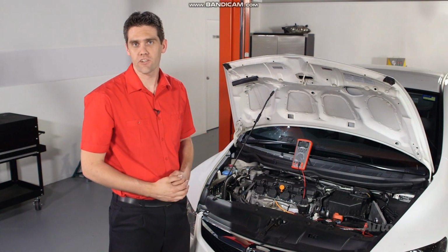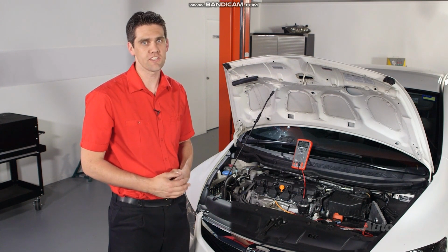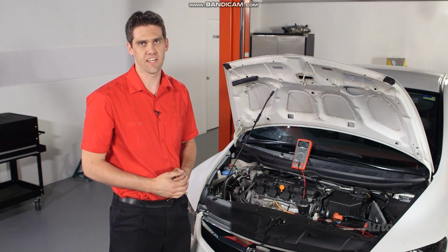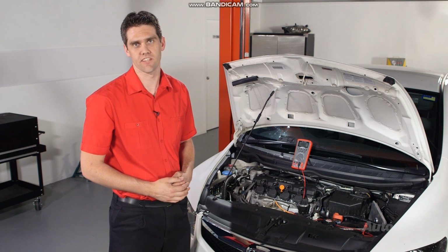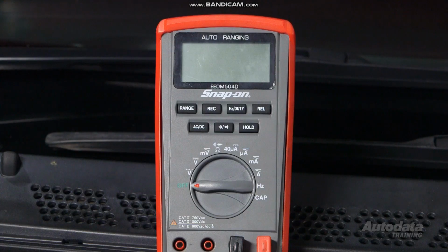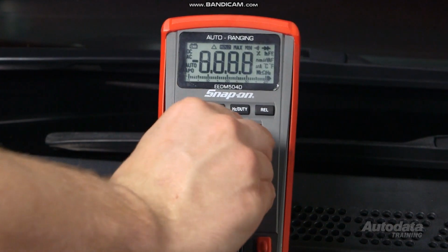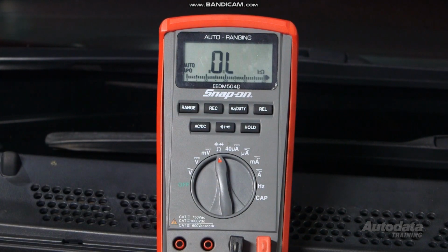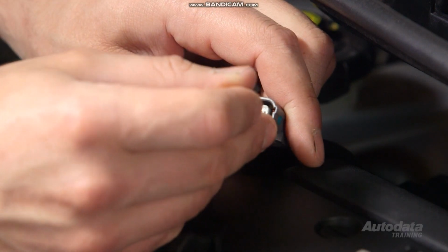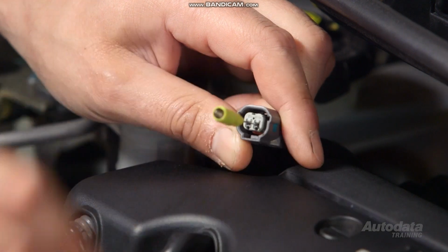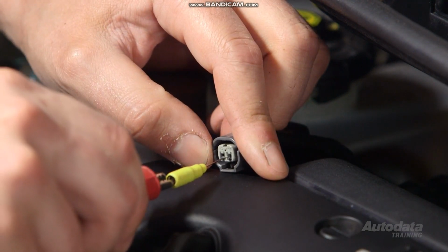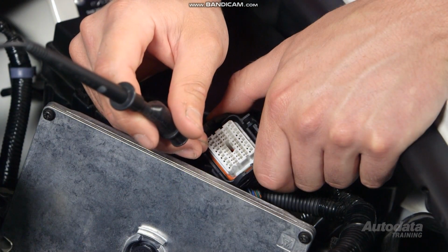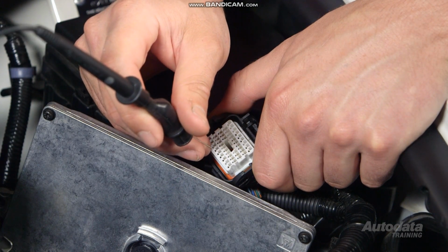If the voltage is now gone, it's either a short to voltage on another wire from the ECM or the ECM itself. To test the harness, set the multimeter to ohms and check for continuity between the signal terminal at the sensor harness connector and each terminal on the ECM connector. If there is no fault found here, the ECM will have an internal short to voltage.